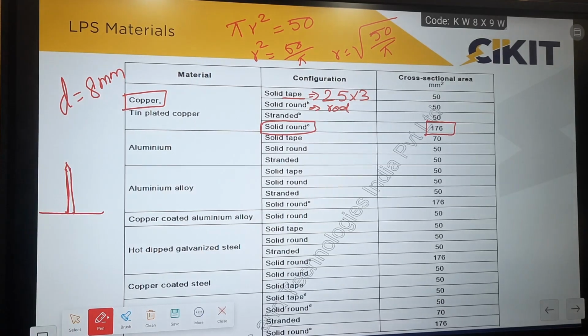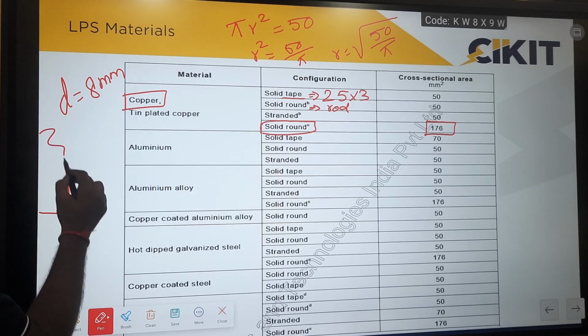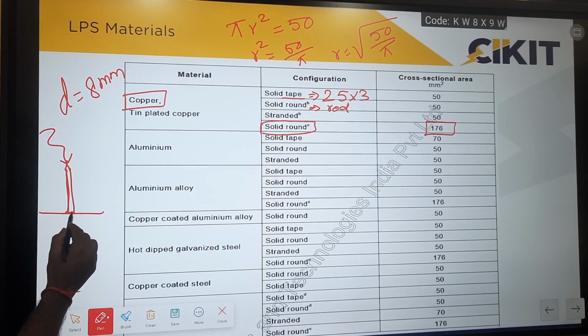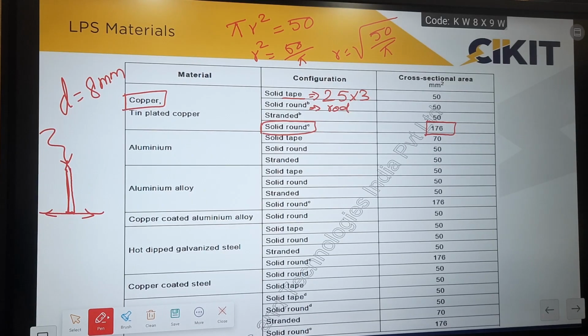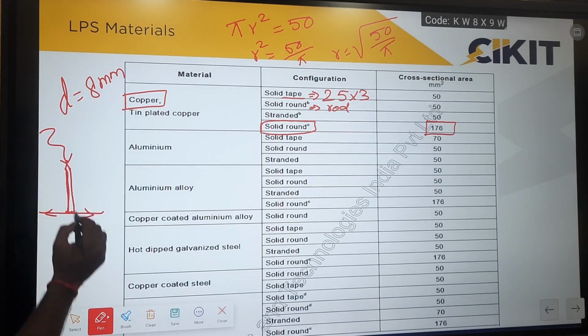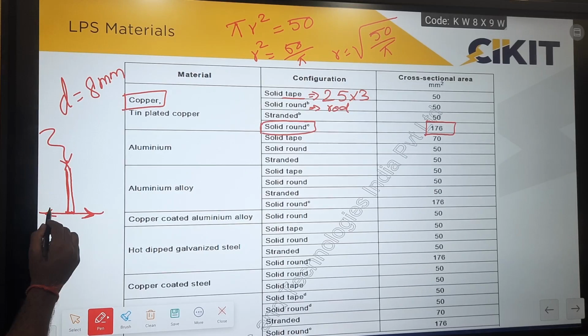And we need to ensure that at every air terminal there are 2 parallel paths for the lightning impulse current to go. So if lightning strikes an air terminal, at the base we need to ensure that 2 parallel paths are provided. If any lightning impulse current is traveling through the rod, it will have two different paths.